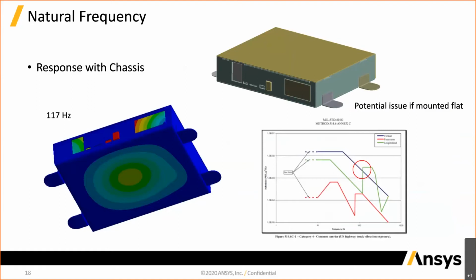With this one, this is a sheet metal box. If it lays there, it also has a standoff in the middle. And you can see that the bottom of that box, depending on how it's supported, could start vibrating. And if there's a standoff that's coming up and attaching to the middle of the PCB right in that area, it could cause problems, because right now the first natural frequency is being driven by the chassis, which is at around 117 hertz. So you can get an idea that you may want to stiffen this box a little bit to get that up higher.